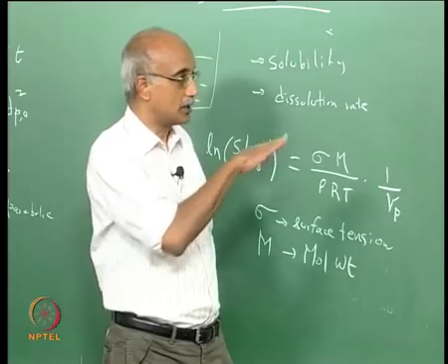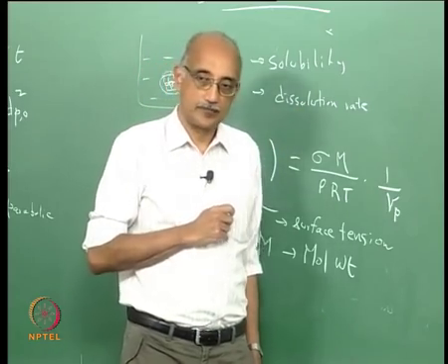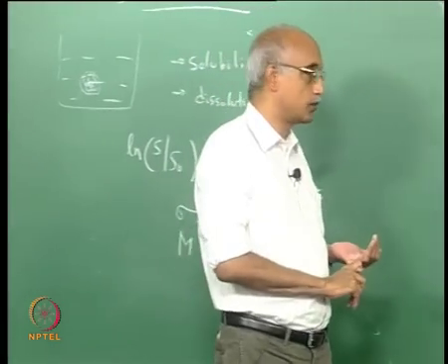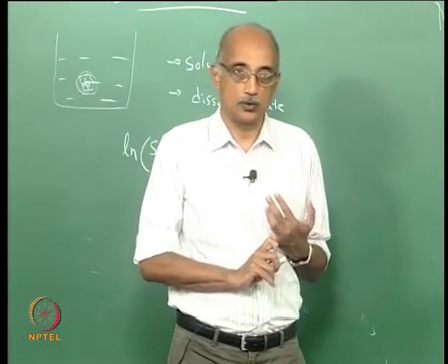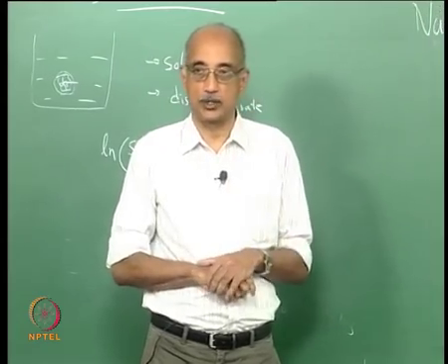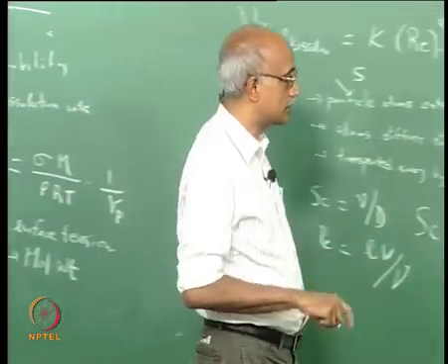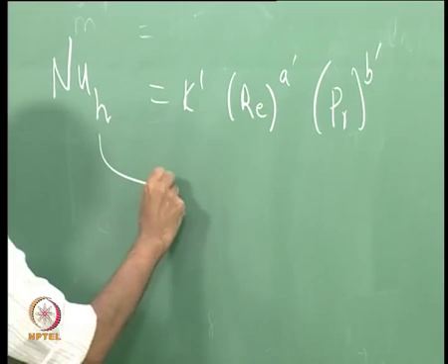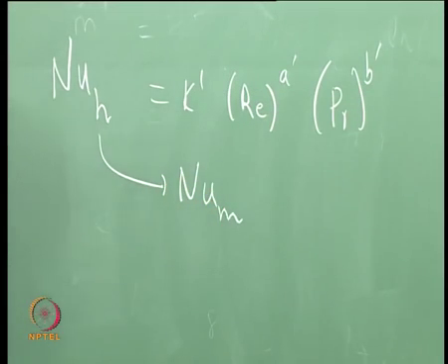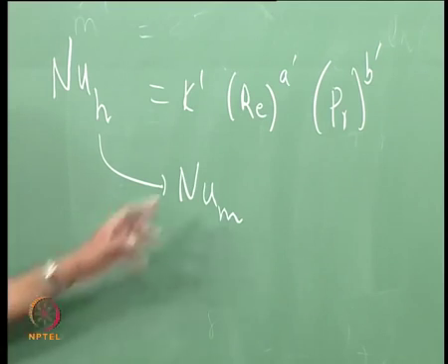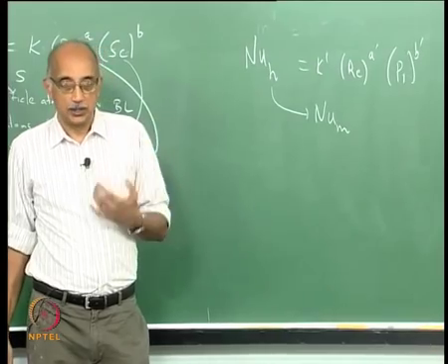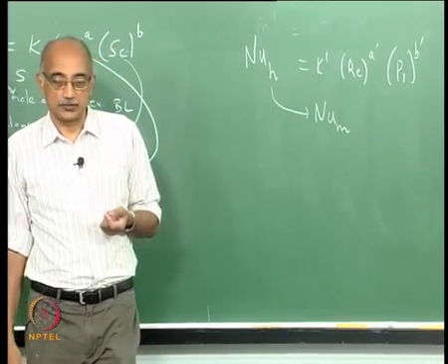And based on your calculation of the Nusselt number, then, as we saw earlier, in the case where there are no phoretic phenomena and there are no inertial phenomena, which is the case in the case of simple dissolution of a powder in a liquid, once you have established the Nusselt number for heat transfer, from this you can extract the Nusselt number for mass transfer by assuming that the functional dependence is the same for both heat transfer as well as mass transfer.